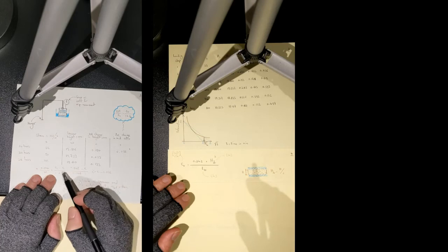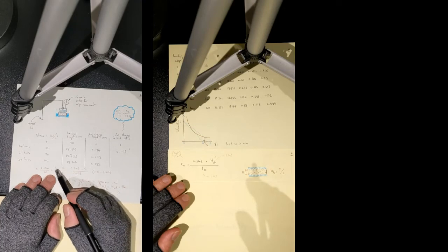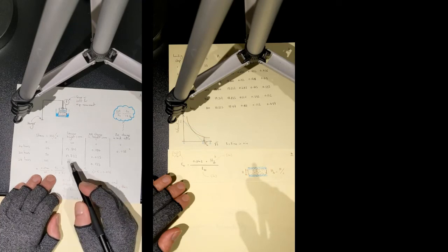That's the change in void ratio, e naught minus e. This is really e naught minus e because it should be a positive number, and we know that the initial void ratio is bigger than the secondary void ratio. You're talking about consolidation, the decreasing void ratio.